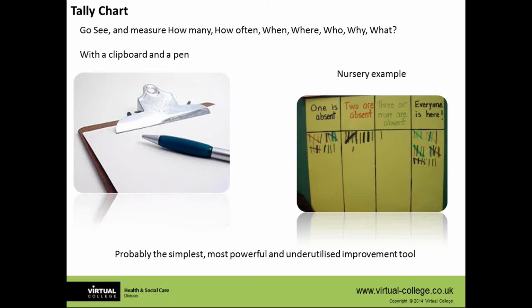All areas should study statistical techniques and implement them as required for internal and external quality audit programs. And basically he advocated the use of 7 basic visual tools of quality so that anybody in the company could analyse and interpret data. And we're going to go through each one of these in turn, just to give you an idea, some simple tools and methodologies. Okay, and they're basically tally charts, bar charts, histograms, run charts, control charts, Pareto diagrams, scatter diagrams, and cause and effects.